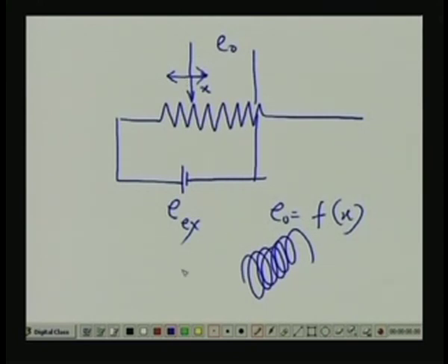you are giving. That type of case does not arise in the LVDT, because in the LVDT I have a core, this bobbin, and inside the bobbin this core is moving, is it not? So there is no physical contact, so life is almost infinite. You can say the mean time between failure is very, very high. Moreover, resolution is also high, because the resolution value here is very, very small.